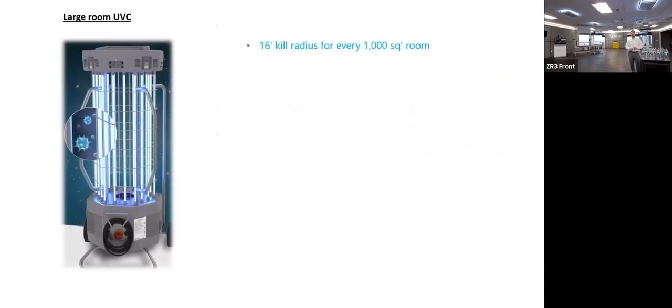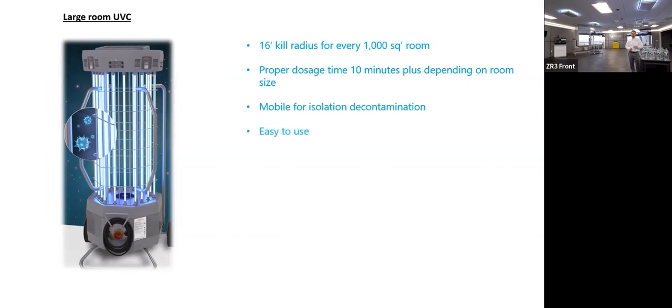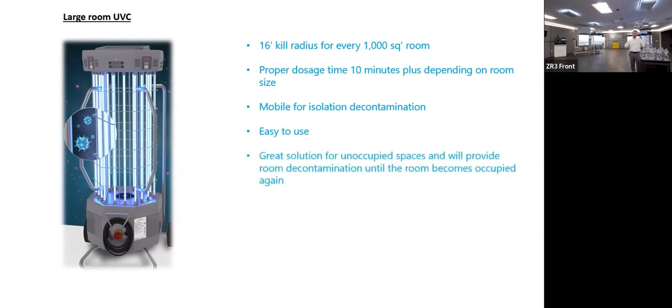And then you have large room UVC. Yep, works absolutely. But this, again, isn't going to address air quality. It's going to deactivate microorganisms on surfaces when it's unoccupied. So, okay, if you want to use these systems to, again, deactivate microorganisms, use it as part of your mitigation strategies or approach, sure, but it's only for an unoccupied space. As soon as we have more people coming into that room, guess what? You can't use this, and you're just going to have pollution and who knows what else coming off of the human.